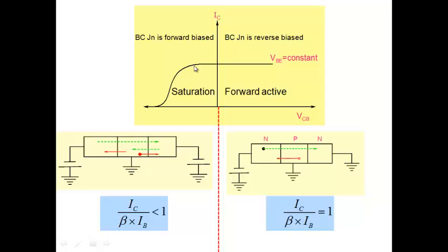So this begins to drop when injection in this region also becomes significant as compared to this, right? When the electron current and the hole current start to become comparable with this, then only the current will begin to drop. So if we take, let's say, that this junction is forward biased by 0.7 as an example. Forward bias on this is 0.7.